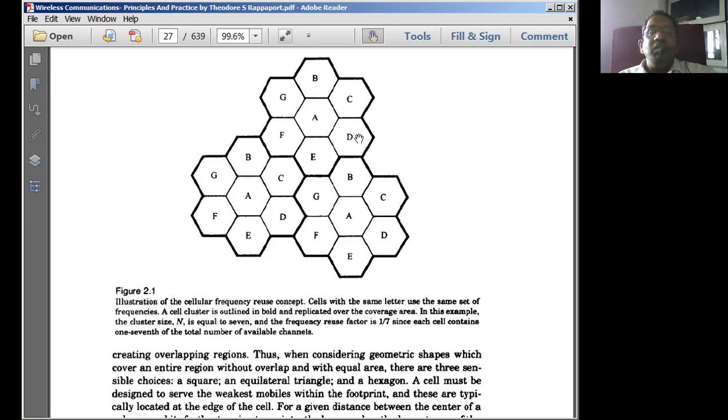Even though they are transmitting the signal simultaneously, these signals do not interfere, even with frequency reuse, due to the distance. As the signal is transmitted to longer distances, say more than 5 kilometers based on the design constraints, the signal deteriorates. So there is no question of interference between the two neighboring cells.